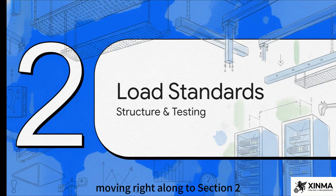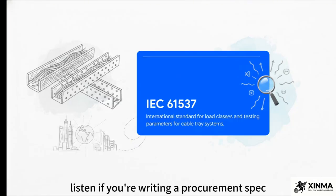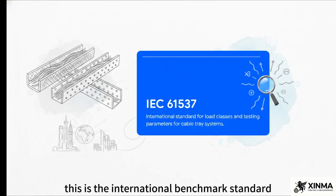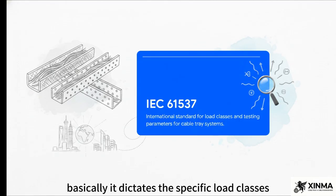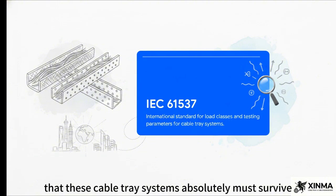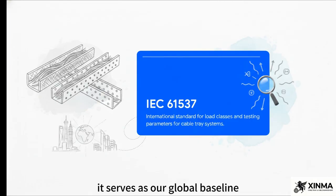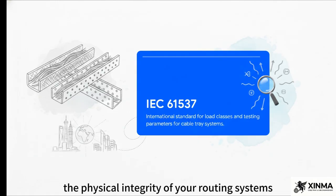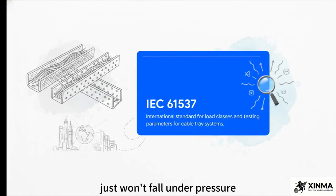Moving right along to Section 2, Structure and Load Standards. Listen, if you're writing a procurement spec, there's one alphanumeric string you absolutely need to memorize, and that's IEC 61537. This is the international benchmark standard. Basically, it dictates the specific load classes and the extreme testing parameters that these cable tray systems absolutely must survive. It serves as our global baseline. Whether you're building out a massive facility in Silicon Valley or Shanghai, this standard is what ensures the physical integrity of your routing systems won't fall under pressure.